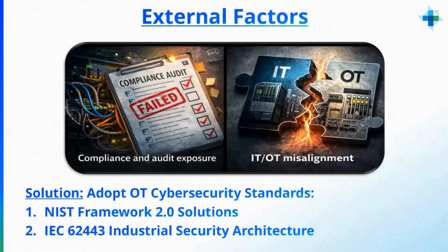So, our last two problems of the day, we have external factors of compliance and audit exposure, as well as IT and OT misalignment. So our solution here would be to adopt an OT cybersecurity standard, like a NIST Framework 2.0 or IEC 62443 Industrial Security Architecture.